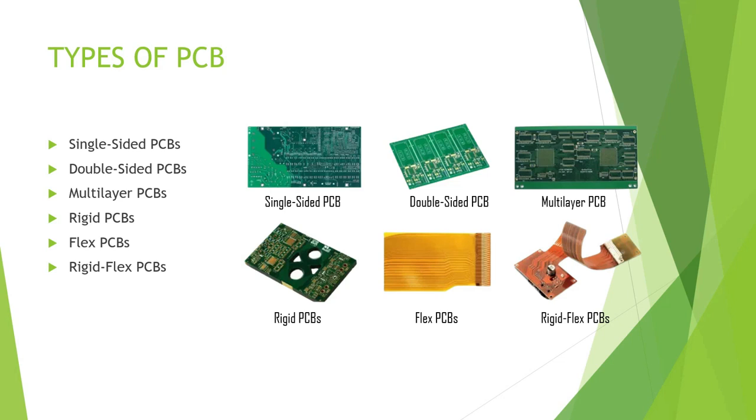And the multi-layer comes under the stack-up position, like a sandwich. In a multi-layer board, three or more conductive layers are possible. Very complex processes are involved in creating a multi-layer board, and medical equipment, file servers and data storage servers come under the multi-layer section. In a multi-layer board, the layer arrangement is called a layer stack-up.